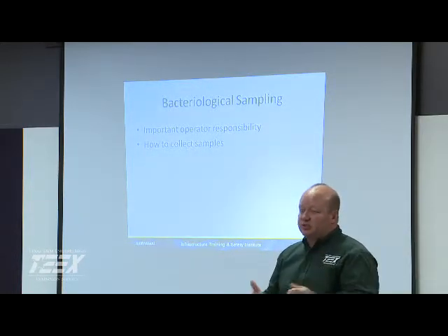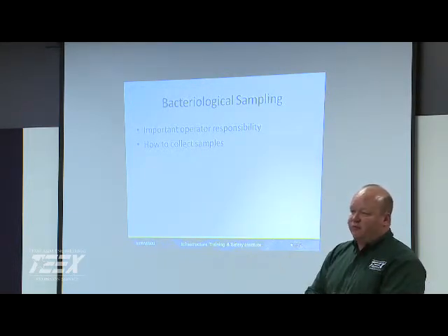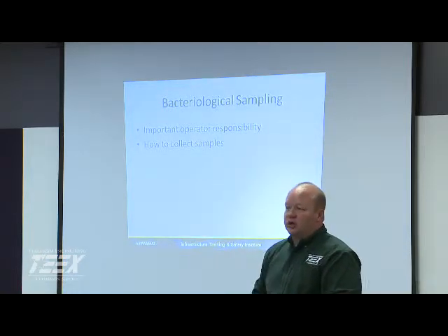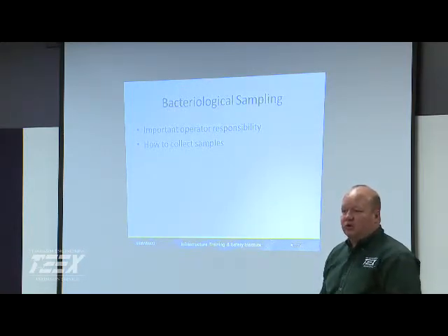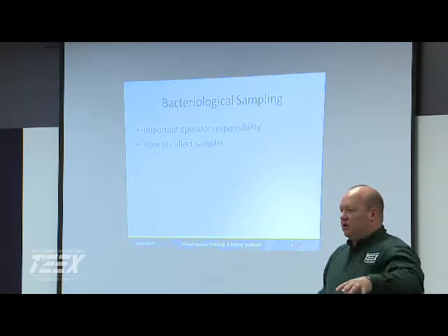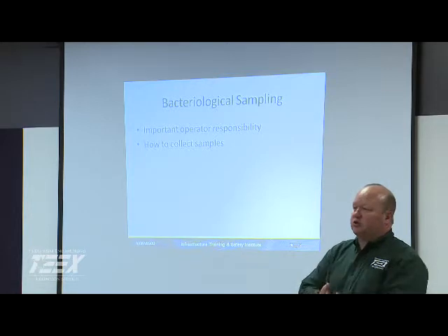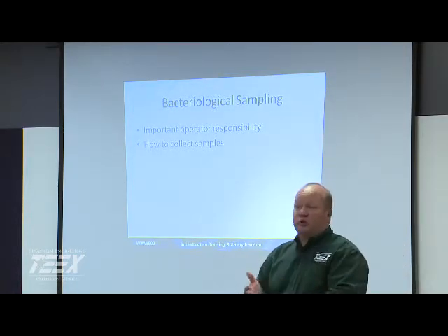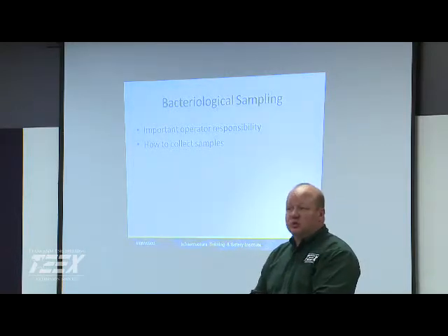In Texas, you have to be a licensed operator to pull samples. Okay. But if they're under the supervision of a licensed individual, I would certainly look at an 8-hour training course or something like that. There's a lot of information available. TEEX actually does, and I know other states too, they have an 8-hour sampling course for either water or wastewater. They talk to you about the different types of bottles you would use for different sampling techniques. Where do you pull them from? When do you not pull them? That's just as critical as pulling a good one, knowing when you don't pull it, because you're going to have a high risk of contamination.